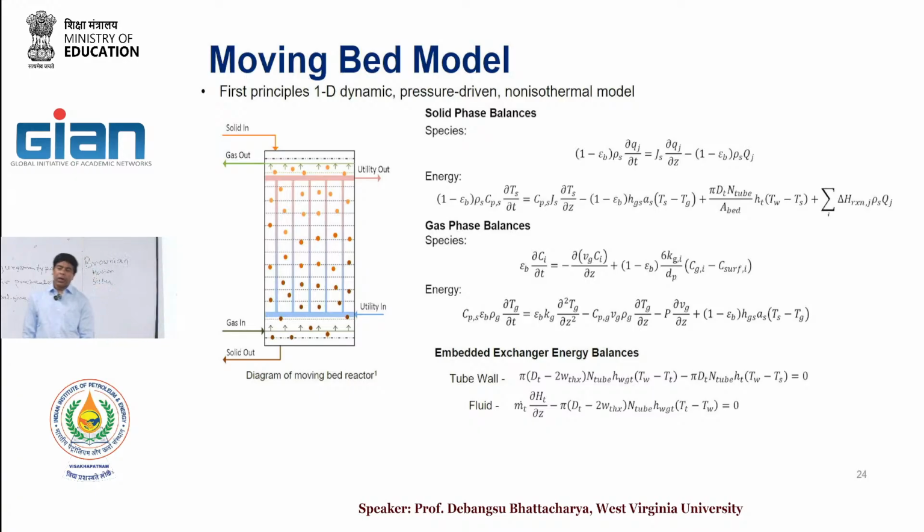The other thing which is very important: so far we talked about the fixed bed systems. What is the biggest issue with the fixed bed system? Pressure drop, okay. Concentration, because we have a fixed material there. Other? Heat. This is one of the biggest things. Like I said, the sensible heat.